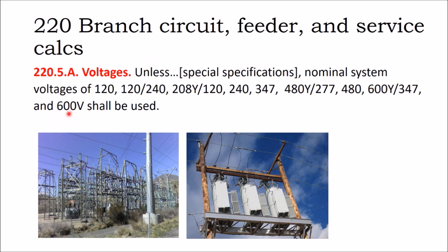So, you have to think about that too when you're doing a ground mount design. Is it better for me to be at high voltage and then go underground with that high voltage to the inverter on the side of the building, or is it better for me to put the inverter out in the field and step down the voltage to 240 volts, but provide some stable voltage going back to the house?